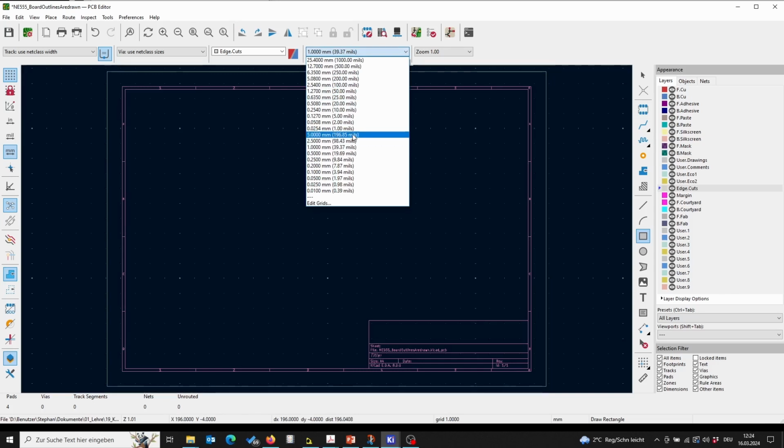You can also have a grid in 5 millimeters or in inches, in mils, since the typical spacing in through-hole technology is going to be 100 mils. This corresponds to 2.54 millimeters. It makes sense during your layout that you change the grid according to the common component you want to place in your PCB. But drawing the outline, we do it with the 1 millimeter grid.